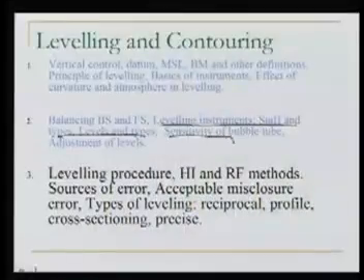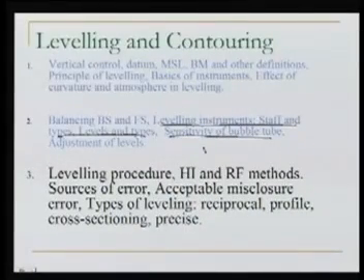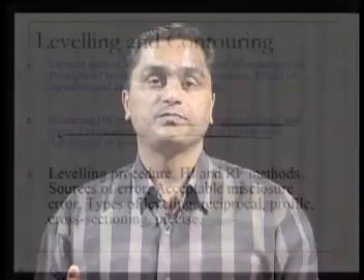We looked into some more things, for example, the sensitivity of the bubble tube, and also if there is some problem with the level, meaning we see collimation error, non-parallelism error, how to adjust that, physically working with the instrument, how to take care of that. Though we know by balancing backsight and foresight, we can eliminate the resulting error. So this is all what we have seen.